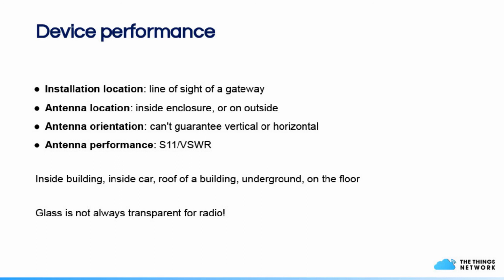Some glass contains metal or has a metal coating. This metal layer will block radio signals. When installing a sensor in a car, plan to get the signal out of the front window, as these are normally designed to allow radio signals through, while the other windows in the vehicle will block it.